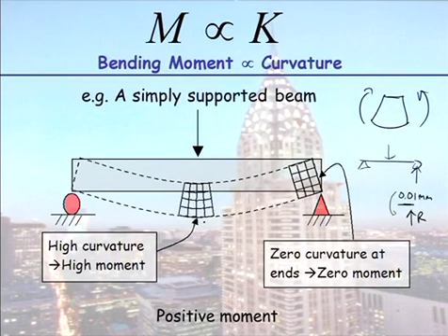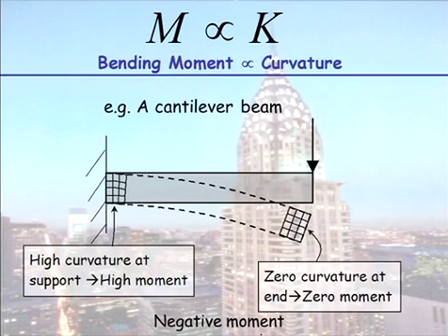So I have the next case, which I won't pull up yet, even though you've all got copies of it anyway. Cantilever. Where do you see the most curvature? People close up. Where is the grid? At the support. At the end here, I haven't put a point load on, but at the point loading, the grid stays rectangular. So for a cantilever, 0 curvature at the end.